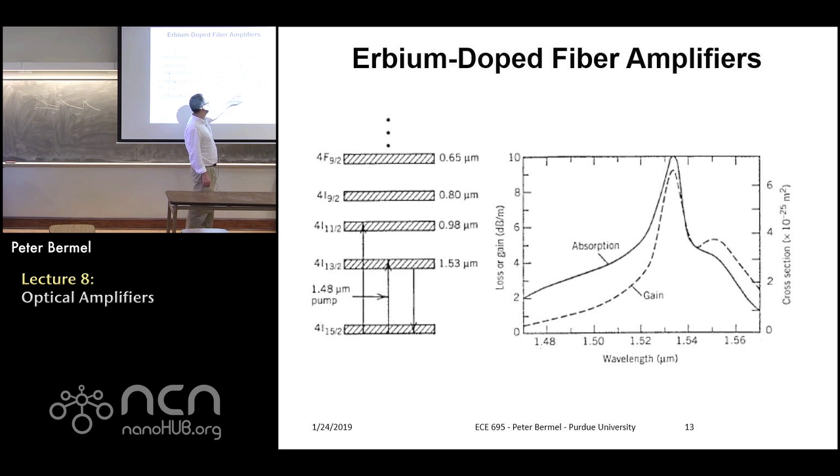And so now you can see why we're so often interested in wavelengths like 1.53 or 1.55 microns, because those match the peaks of the gain of this erbium-doped fiber amplifier. So that shows you that this is very appealing in terms of getting very high gain values. And then the additional advantage of 1.55 is that it's separated further from 1.48, so that further reduces crosstalk.